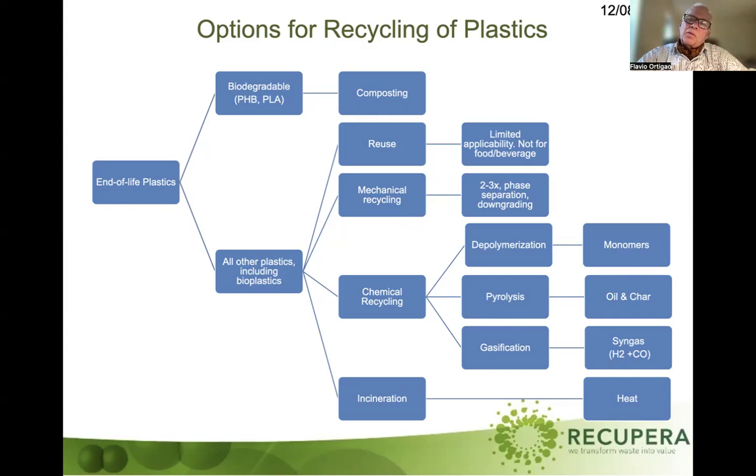You have to compare those plastics to fossil oil, because nobody asks these questions of oil when it is used as an energy source. So, plastics compared to oil: well, mixed plastic has everything. Mixed plastic is 39 megajoules per kilo. A purified plastic, HDPE, high density polyethylene, has around 44, and oil has around 45. So it's very close.